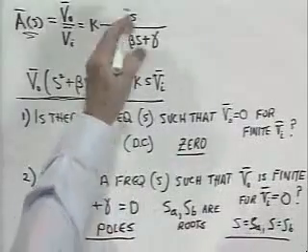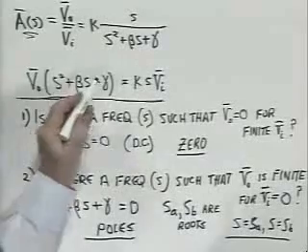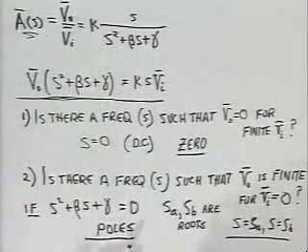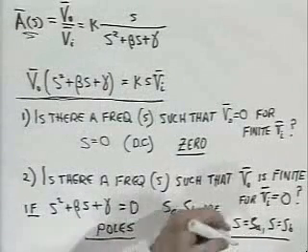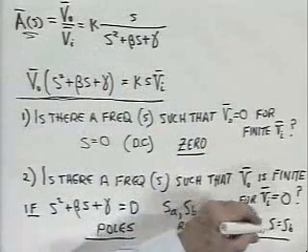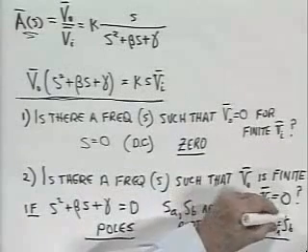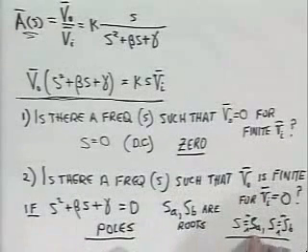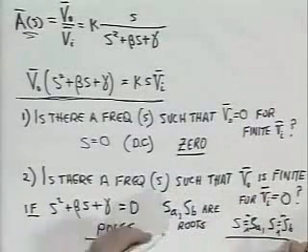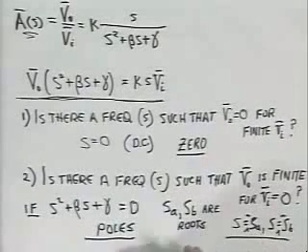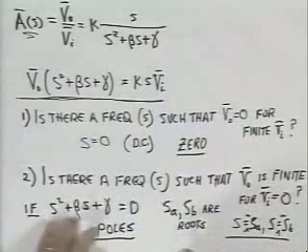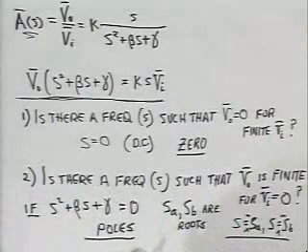So this transfer function has one zero that happens to be at the origin. It has two poles which are at S equals minus S sub A and S equals minus S sub B, if by S sub A and S sub B, I mean positive numbers. When S equals minus S sub A, the function vanishes. When S equals minus S sub B, the quadratic vanishes.